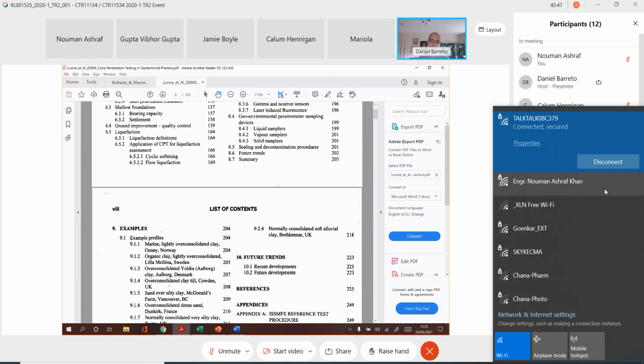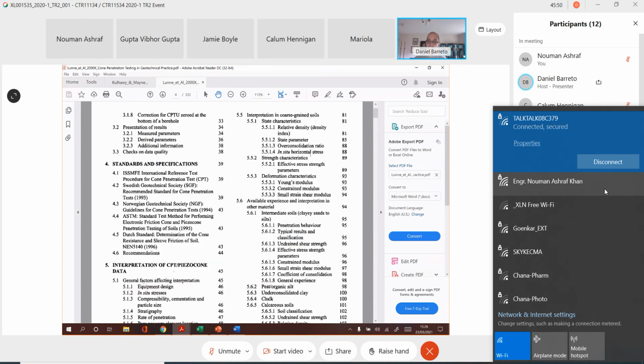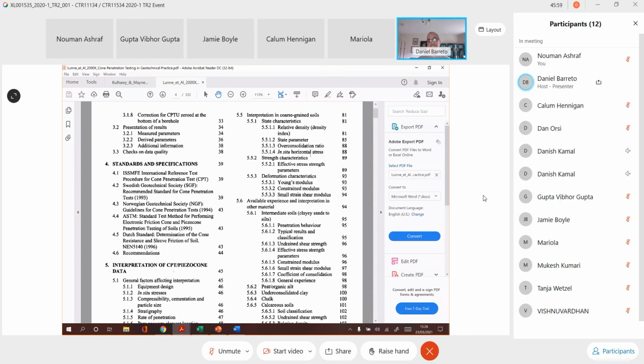But the rationale, what I'm showing you, is that we have so much experience on CPT test results that you find quite a lot of these relationships. And the biggest challenge nowadays is not really about the design method itself. You'll see next week that actually that is quite straightforward. It's a standard recipe. But what is really difficult is to decide which relationship do you use between CPT test data or results and the properties that you need to input in the design.